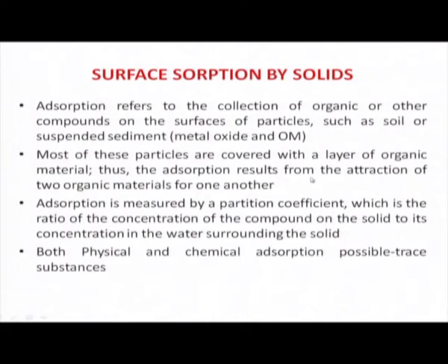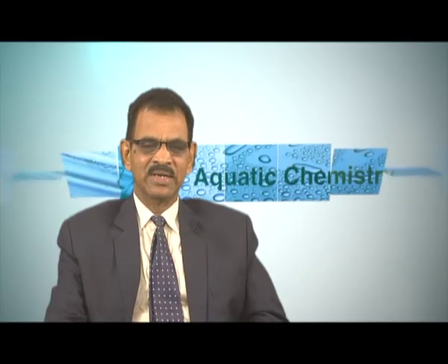Thus, adsorption results from the attraction of two organic materials for one another. The adsorption is measured by a partition coefficient value, again not only for liquid; this is also governed by the partition coefficient value, which is the ratio of the concentration of the compound on the solid to the concentration in the water surrounding the particular solid in the aquatic system.